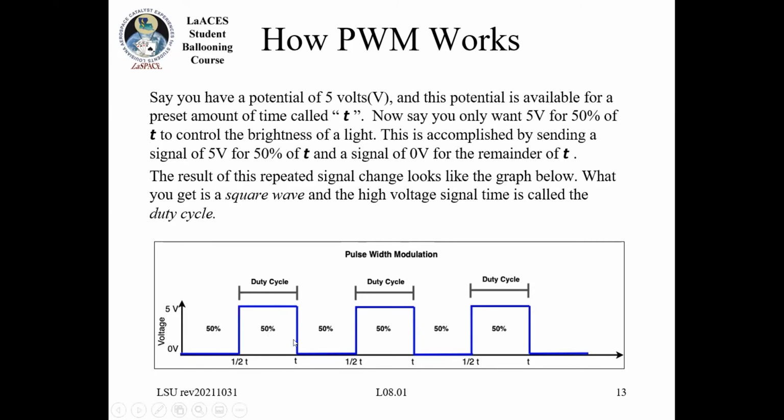And the point is I'm going to repeat this. This only works if I know that this pulse is some fixed width, right? Because if this total period length changes, I can no longer tell what percentage it was on. If that length can vary, when I look at the positive pulse part, I don't really know what percentage it was.